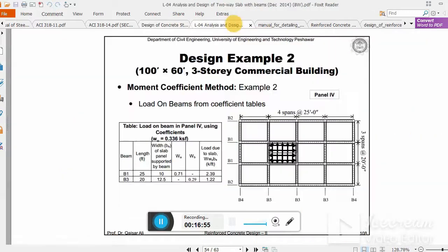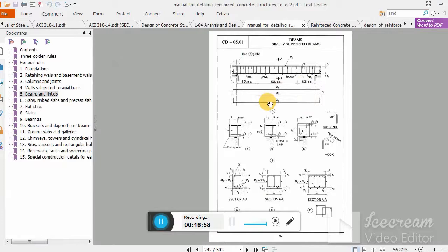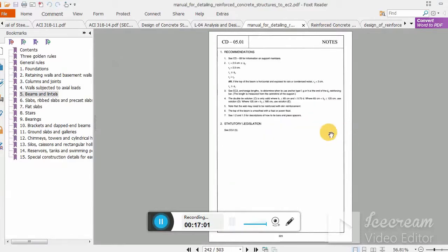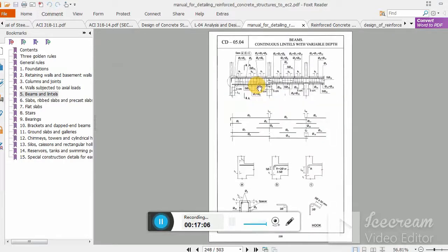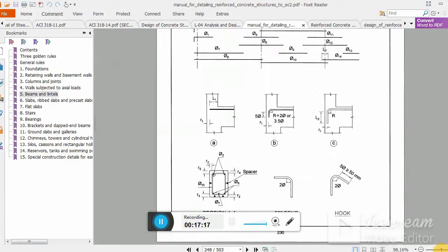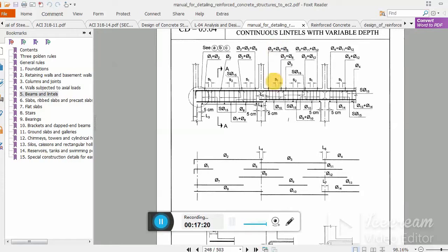Now, a very interesting thing I want to show you is lapping of bars in beams. In part number 2, or lecture number 2, I mentioned where we have to provide lapping. This is also according to Euro code 2. In a continuous slab or beam, because the beam lapping principles are also applied the same for slab, you see here the top bar is continuous.